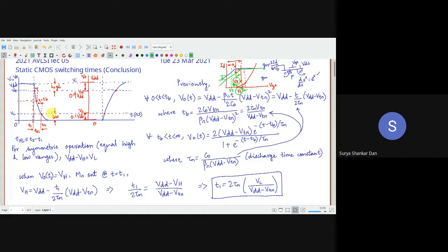Similarly, in case of this also, we will see in the next class how industry will actually overestimate the TPHL and TPLH values, overestimate with respect to what we are calculating. The accurate value will always be less than the value which is recommended by industry. And then, for example, over here we found out why the Vt overestimation is helpful from an IC point of view.